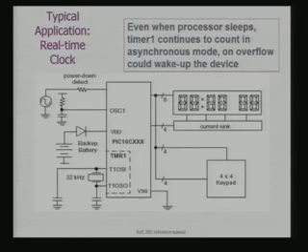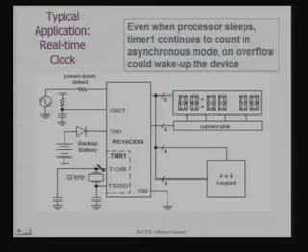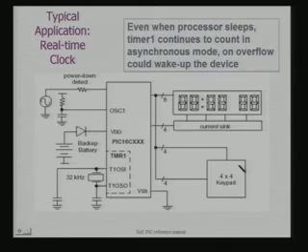And the timer works on its own from an external clock source. So I can connect an external crystal to this timer. In fact, what I have shown here is that we have connected an external crystal. These are the inputs to timer 1. And this can be the keypad interface for user interaction with that clock. In fact, you can consider this to be a very simple embedded system built around your PIC.